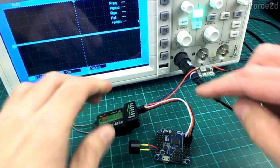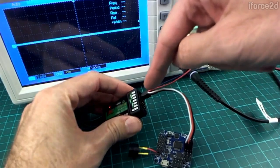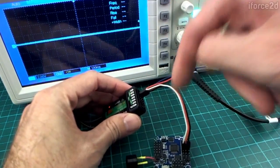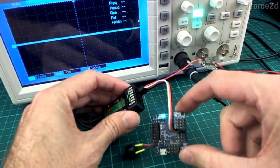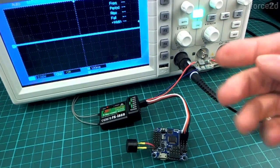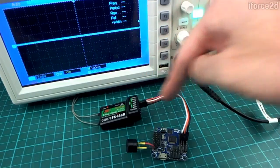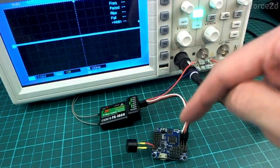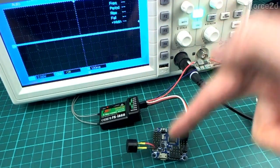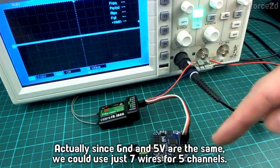So what that means is that if we wanted to use this type of PWM communication, we're going to need lots and lots of wires. We're going to need 5 sets of wires, 15 wires in total, coming from here to here, and that clutters things up quite a lot. It's the old-fashioned way of doing things, the way that servos would have worked, because on a plane you do actually need separate wires going to each servo, so it was necessary to do this. But with quadcopters, where we just have one thing talking to another one thing, having 15 wires between just these 2 things is kind of silly.